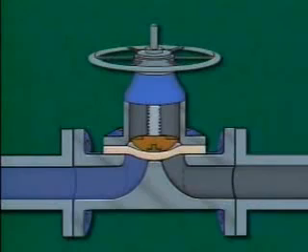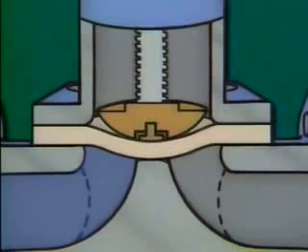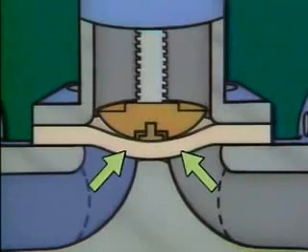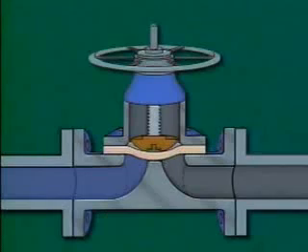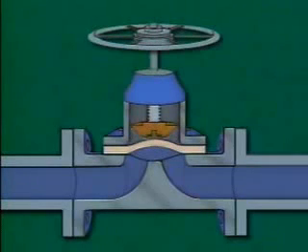As its name suggests, a distinguishing feature of a diaphragm valve is a flexible diaphragm that's used instead of a disc to seal against the valve seating surface. A diaphragm valve also has no packing. Packing isn't necessary because the diaphragm forms a boundary that keeps fluid from leaking along the stem.